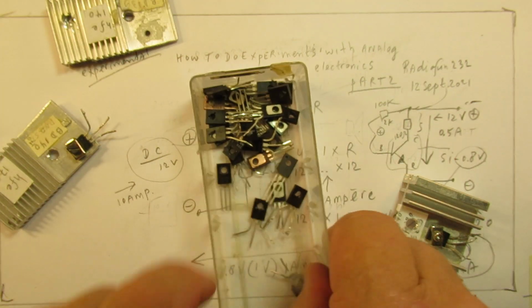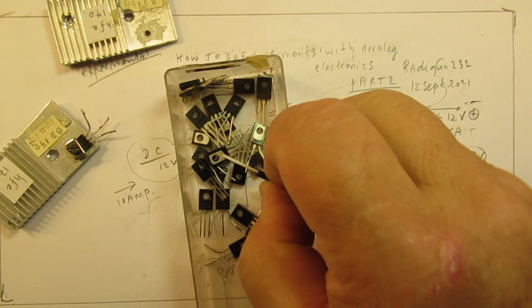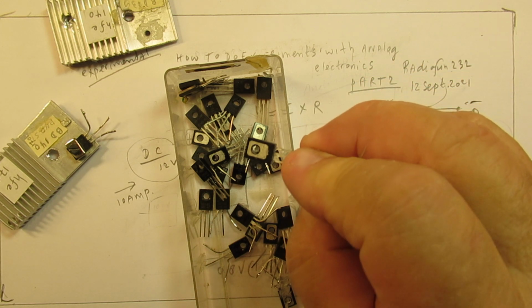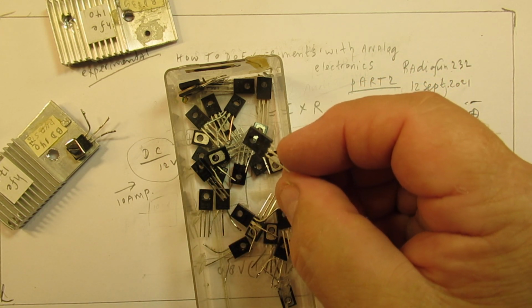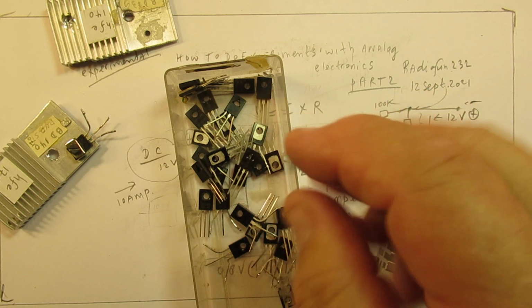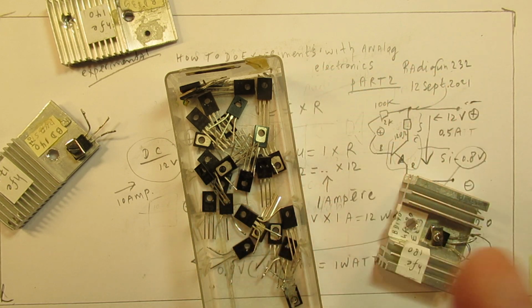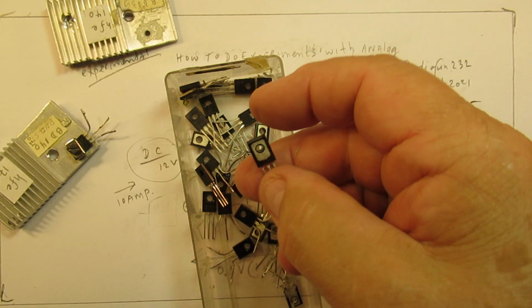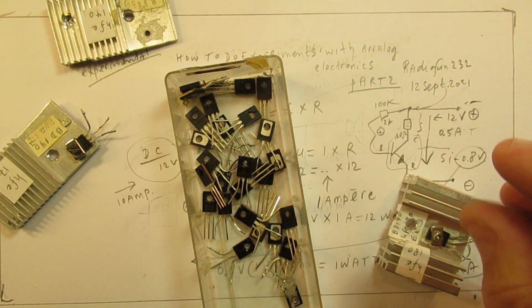But on the other hand, when we have this transistor, for instance, the BD139 and the BD140 are made to dissipate surely 1 watt on a heat sink, and here's that metal plate, you can cool it. Surely they are able to do that, and they can even go to approximately, in theory, 6 watts, but in general I always use them only for 4 watts approximately.